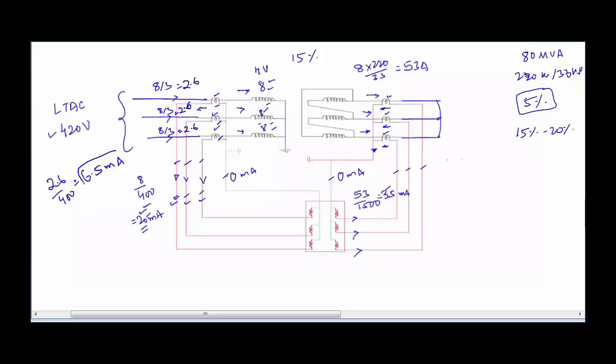Now 6.5 milliamperes is not a high value of current, so its measurement is not easy. Measurement of such a small amount of current is not an easy task if we do not have an accurate tong tester, or if we are not carrying an accurate ammeter. For this particular case, if we assume that we were carrying a tong tester whose accuracy was 10 milliamperes, then the measurement was not possible, because that tong tester is not going to measure accurately if the current magnitude is below 10 milliamperes. So if the current has a magnitude of 6.5 milliamperes, there is a probable chance that the tong tester is going to give a value of 0 milliamperes. So even if there was a flow of current in all these three phases, we were going to measure a current whose magnitude is 0 milliamperes, which is just because of the accuracy limitations of the measuring device.